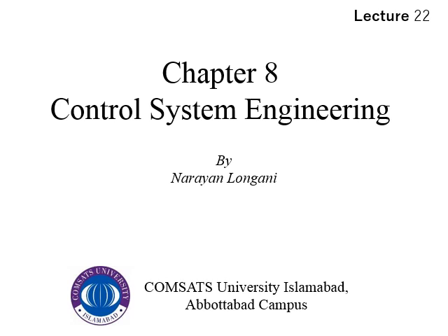Fifth rule defines the path through which poles will reach the location of open loop system zeros which are at infinity, with the help of asymptotes. And the sixth rule we studied was j omega crossing. J omega crossing gives us the frequency of oscillation, and it also separates left half plane from the right half plane.